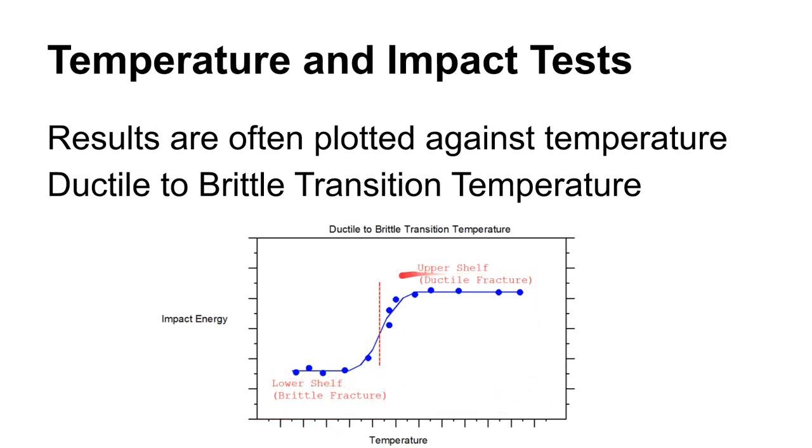Then what we would see is that some materials would start to lose their toughness as they get colder. Okay, so this is a very important factor when you're talking about toughness, understanding whether or not that material exhibits this ductile to brittle transition phenomenon or not. Because here you see much tougher samples at higher temperature, but then you go through this zone here, at this temperature here, it just drops, and we have a much more brittle material as it gets colder.